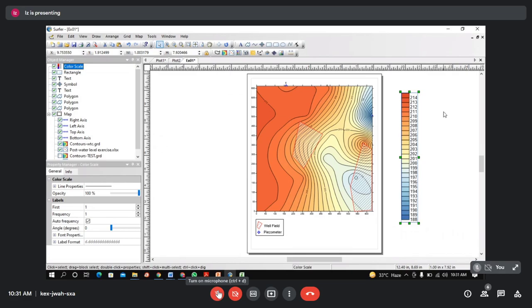Okay. So now, who will tell me about groundwater flow direction? So this is a very simple thing. Groundwater flow direction we can know from the equipotential lines, right? The flow line will be perpendicular to the equipotential lines, right? This we know from our previous classes, right? Okay. Yes. Okay.